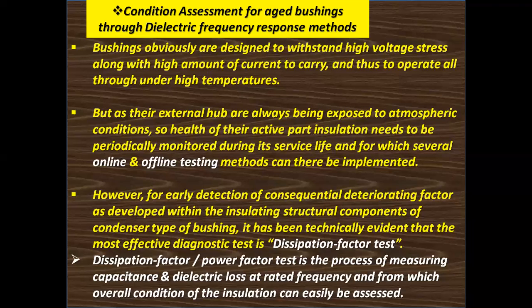Dissipation factor or power factor test is the process of measuring capacitance and dielectric loss at rated frequency, from which the overall condition of the insulation can easily be assessed. As we are discussing capacitance graded bushings, capacitance and dielectric loss both are very important for assessing the insulation condition.